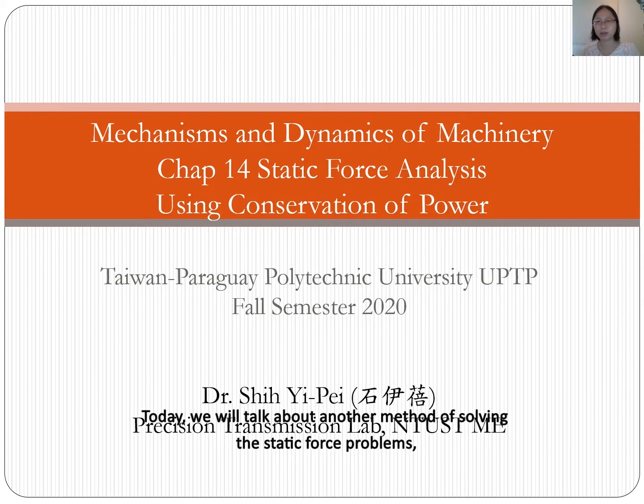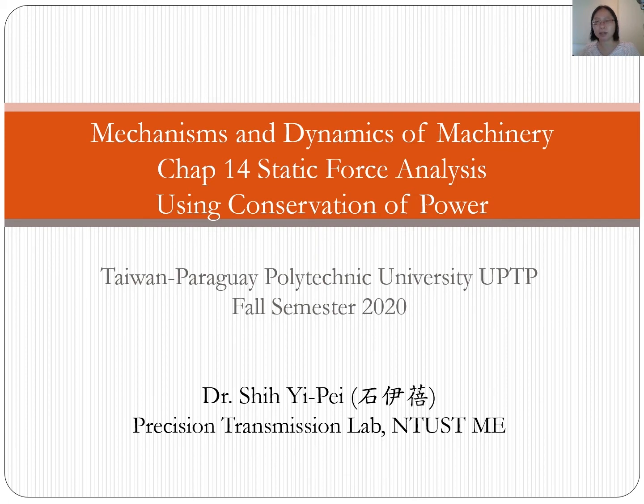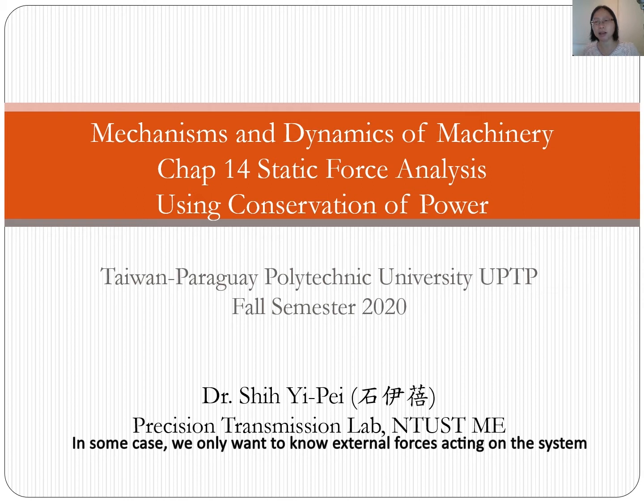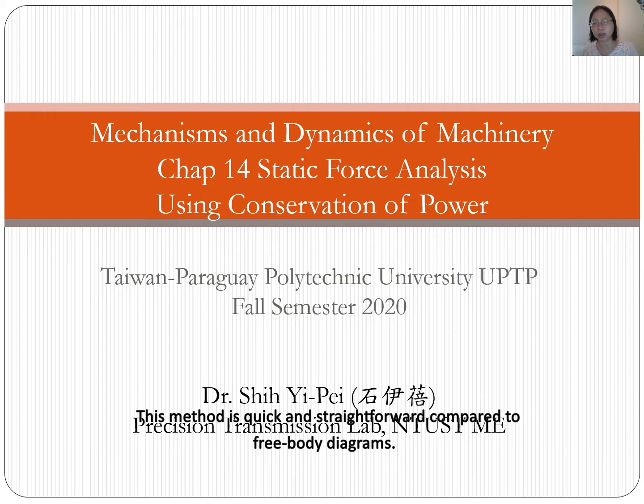Hello everyone. Today we will talk about another method of solving the static force problems, conservation of power. In some cases, we only want to know external forces acting on the system rather than internal forces on the system. For example, action and reaction forces on the joints are internal forces. This method is quick and straightforward compared to free body diagrams.